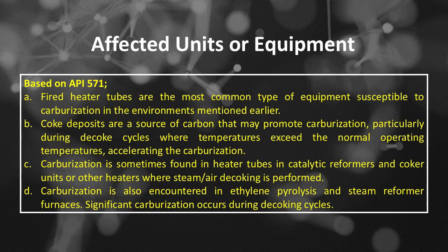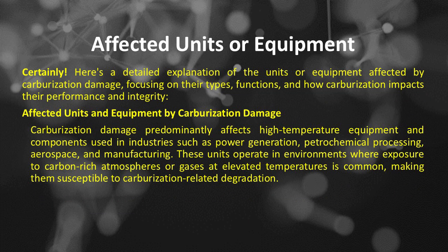Carburization is also encountered in ethylene pyrolysis and steam reformer furnaces. Significant carburization occurs during decoking cycles. Certainly. Here's a detailed explanation of the units or equipment affected by carburization damage, focusing on their types, functions, and how carburization impacts their performance and integrity.